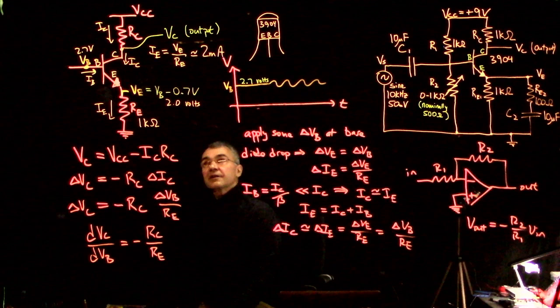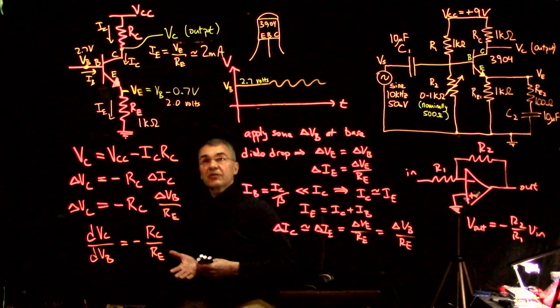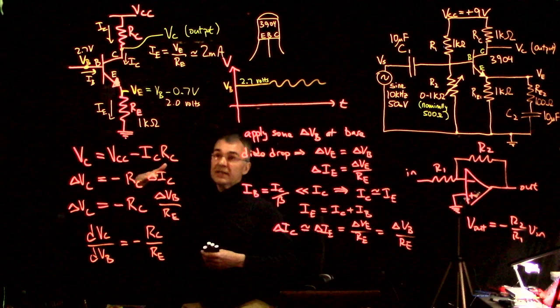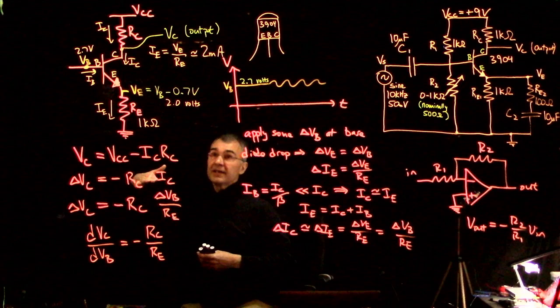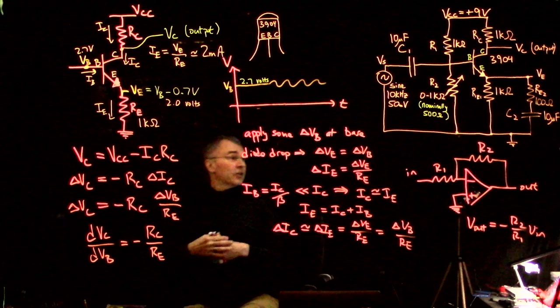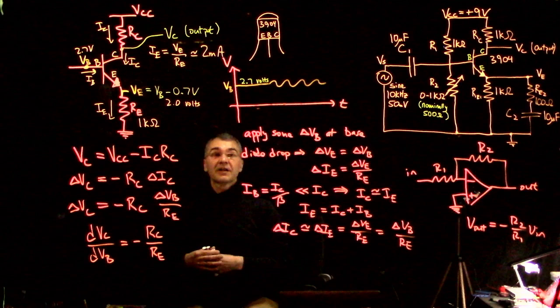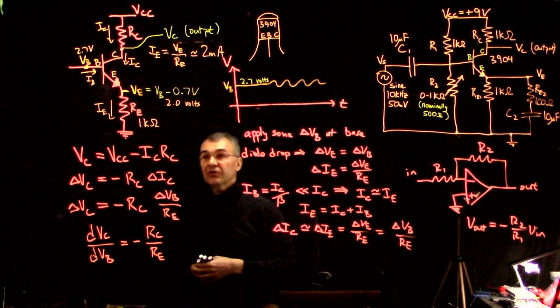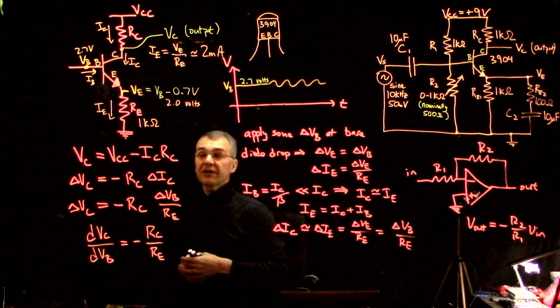So once again, we always start by asking what's happening at the base, and we arrange things so that the transistor is active. And then we start out setting things up the same way we did for the emitter follower. So we have this resistor called the emitter resistor between the emitter and some fixed voltage.